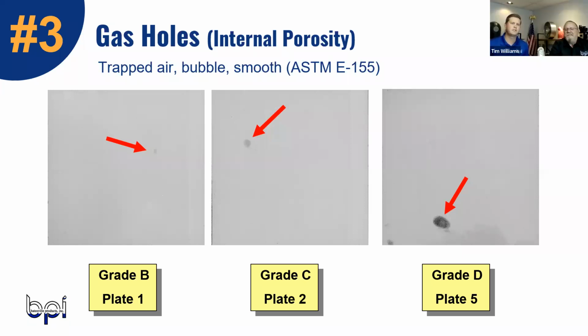Sure, and I think it could go the opposite way too, right? You could go too slow and not get your casting to fill out. So there's definitely a sweet spot in the middle ground that is ultimately the area we want to achieve, so that we're eliminating any of the gas holes, especially in permanent mold. Yep. But not making it so the part doesn't fill out, because you still want to make the part the way the customer is requiring it. So great.